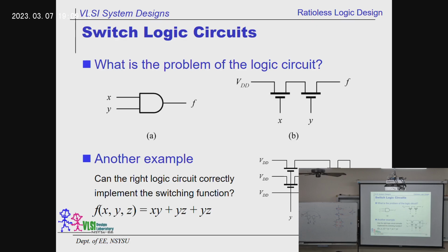But the reality is, even though you give a high signal to drive these two transistors, you are not going to get exactly the high voltage. Because as we said before, if this point here is VDD, then this is also VDD. For this device, it will not turn on. It's dead. So you're going to get at most this much. That's all.